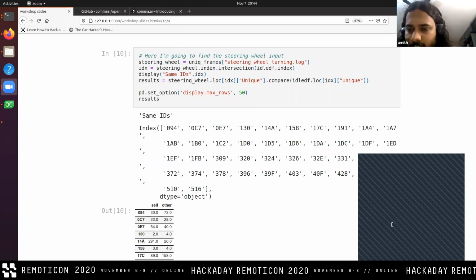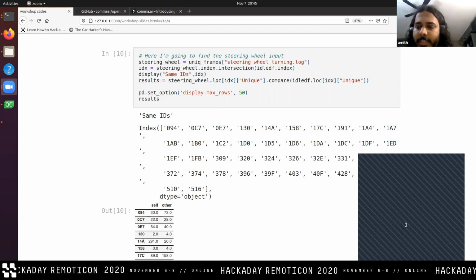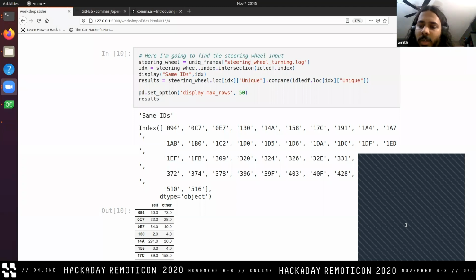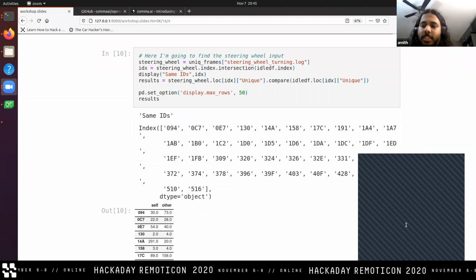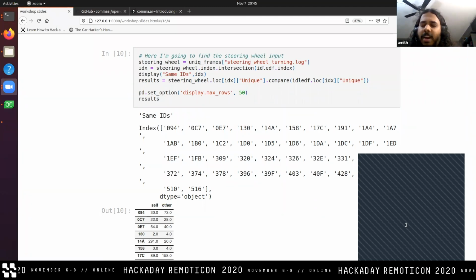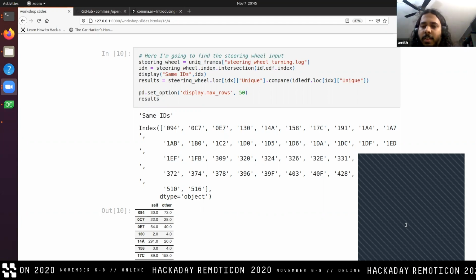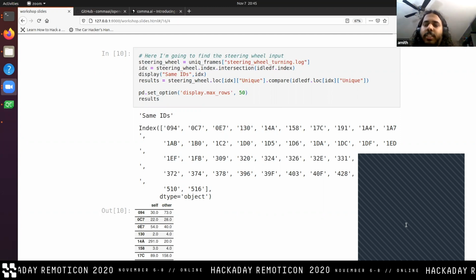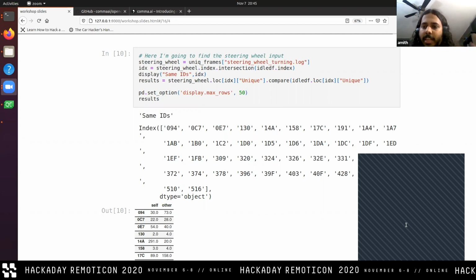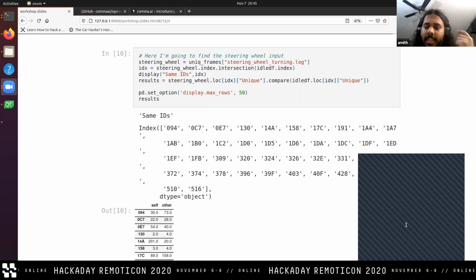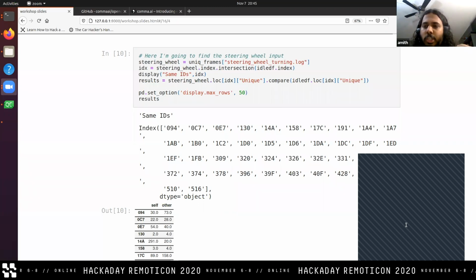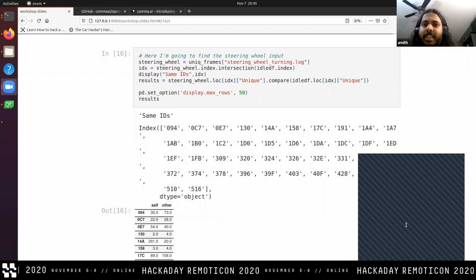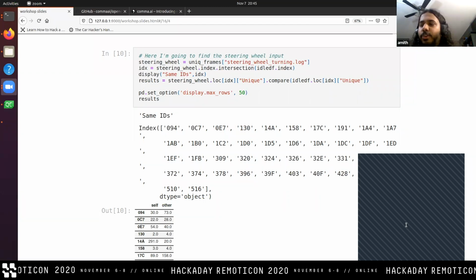So Will asks, does OBD2 specify a standard set of messages so we can work on any vehicle? Yes. I think they define like 10 or something. Some of them the manufacturers have to implement, and some of them they don't have to. But it's very, very basic information, so you're not going to get anything useful out of it.